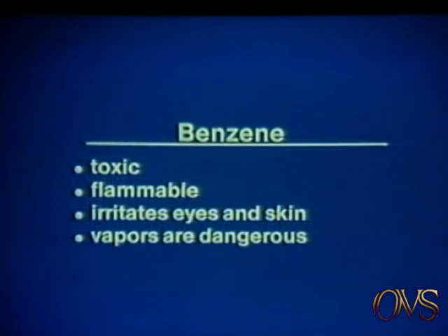Benzene is a water-clear liquid with an aromatic odor and is the most hazardous hydrocarbon pumped in APL in terms of toxicity. Benzene will cause a slick on water and has a flash point of 12 degrees Fahrenheit. Its flammable vapor limits are 1.4% to 8% in air. Benzene vapors are heavier than air, so they may accumulate in low spots.